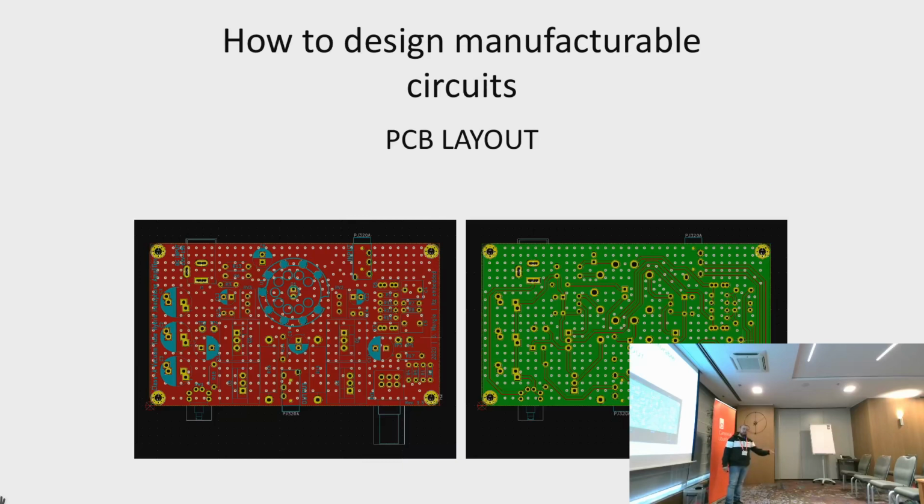So before designing, starting with layout is very important to set this properly, because this will also affect the cost of your circuit. If you relax some of those rules according to the price the PCB manufacturer can offer you, nowadays you can get very cheap PCBs. For example, a simple 2-layer with the most relaxed rules can be produced, like 10 pieces for $5. So it's really something that is very affordable, and was not true when I was studying.